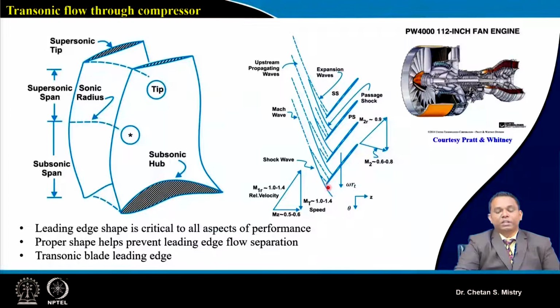Now here in this case, when the flow is entering, because of the presence of my leading edge, which is of slightly smaller curvature, that is what gives the bow shock to be formed. Because of the suction surface, here we will have expansion fans formed. We will be discussing the flow structure for this kind of configuration in detail, but at this moment